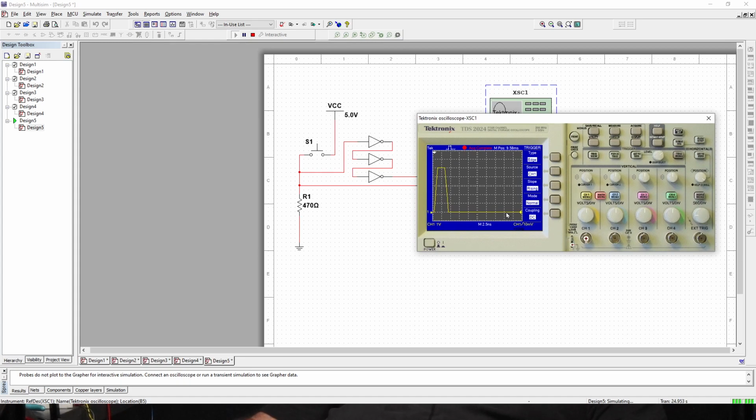All right, now there's something more we can do. We can adjust the volts per division. If we make it more sensitive, then the signal is going to go off scale as far as displaying. It doesn't change the signal. The signal is captured. We're just trying to adjust to the point that we can actually see the whole thing in the most comfortable way possible. And then we want to get it as big as possible without going off the screen. Right, so okay, that's as far as we can go.